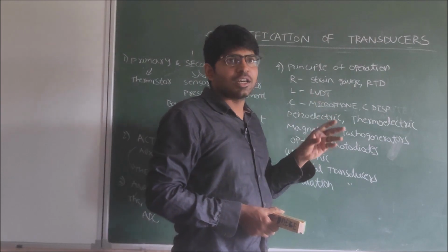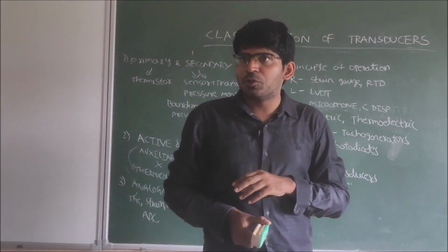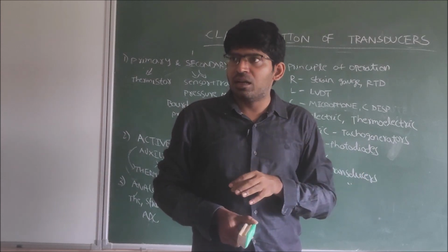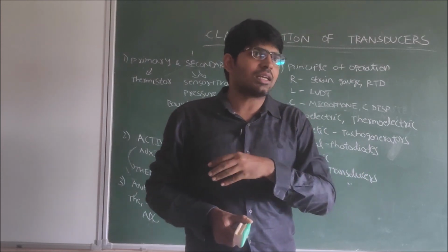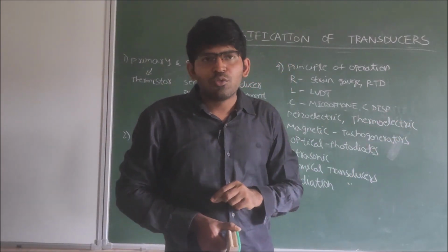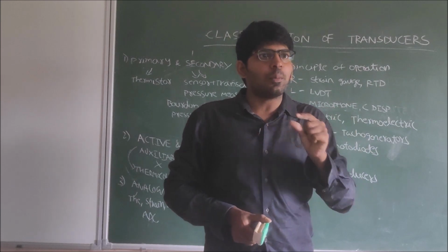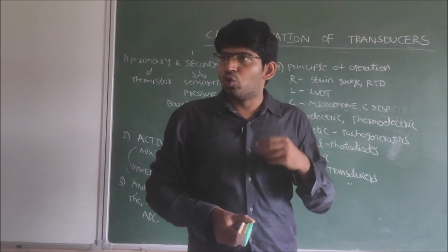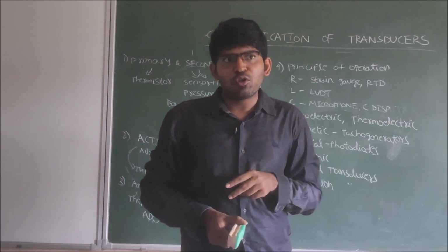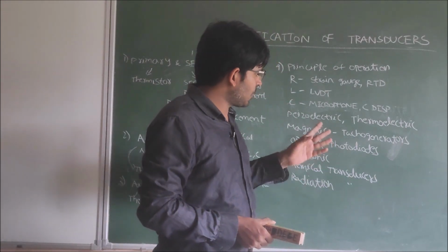Next one is the piezoelectric transducer. In this, we use the piezoelectric material property. It converts mechanical changes into electrical signal changes. And in thermoelectric transducers, we use two different metals which are at different temperatures. The difference in temperature information will be converted into an electric signal.